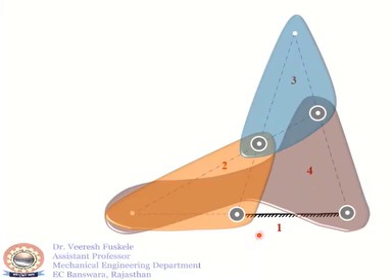So this is A, B, C, D according to our previously taken notations, and also these are the instantaneous centers I12, I23, I34 and I14 respectively, as we have determined them by inspection. Now, applying Kennedy's theorem, we have seen that I13 is located at the point of intersection of these two lines: the line joining I12 and I23, extended, and the line joining I14 and I34.